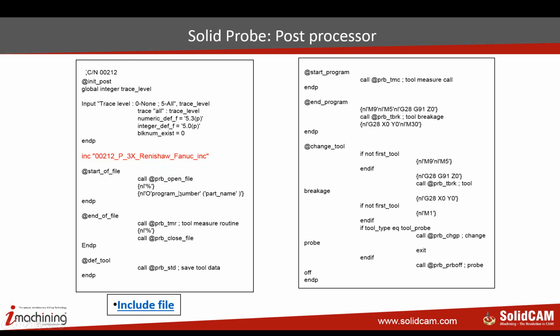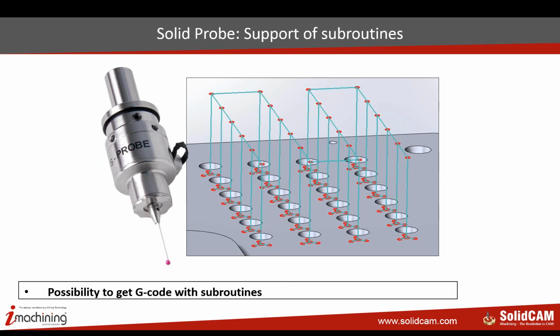At the end of this webinar, I will take a regular post, a standard post processor without probe, and we will add this include file command, and I will also tell you about a few things that you need to pay attention to. Of course, as any other operation in SolidCAM, the probe also supports the subprograms, the subroutines.